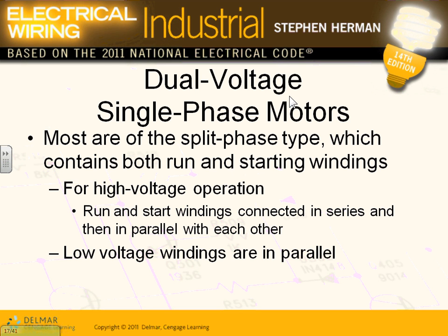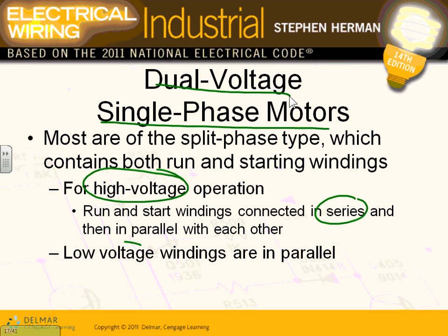Single phase, I don't want to talk too much about single phase. Same thing, guys. They all come with dual voltages for single phase. They can get you high voltage. Can you guys write yourself? High voltage always goes with series. You put the coils in series. And low voltage always goes with the word parallel. If you understand this one, you would never go loose in transformers.